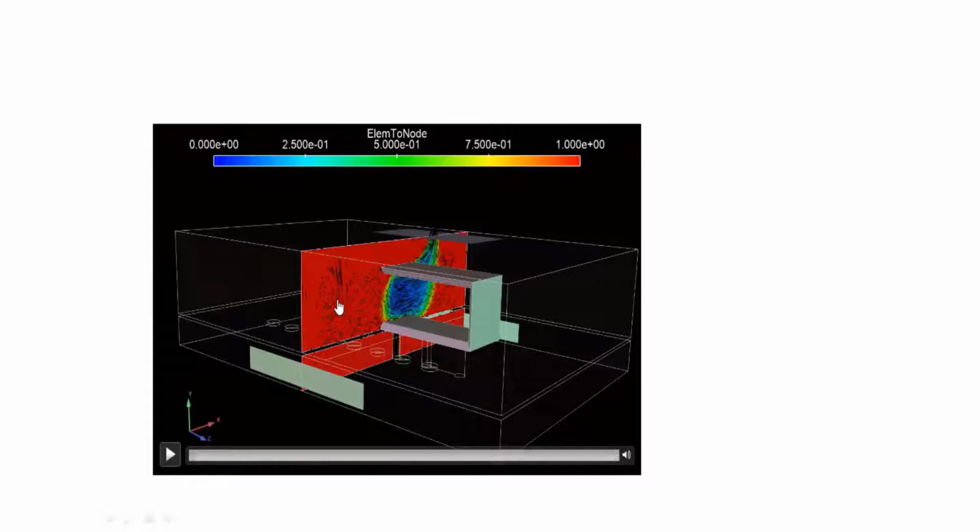Now if you closely look at that, why is the outlet at the top, right? We have provided the outlet at the top, and you can see that the vectors are moving upwards. So why? Because when the cool air is coming and getting sucked into the cabinet, it is picking up the heat, and when the temperature of the air increases, its density decreases. Correct? When the density decreases, it is bound to move upwards. So that's why the outlet is up.